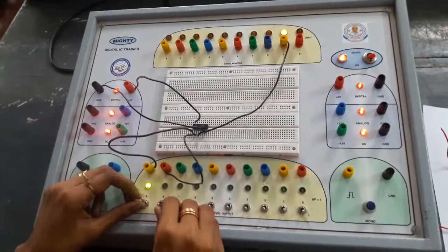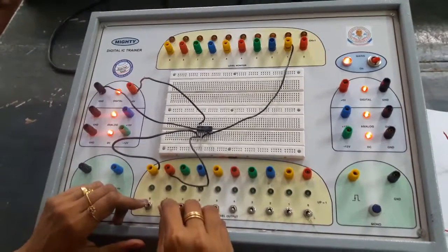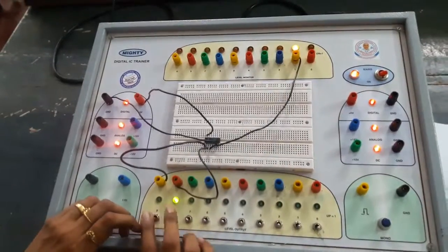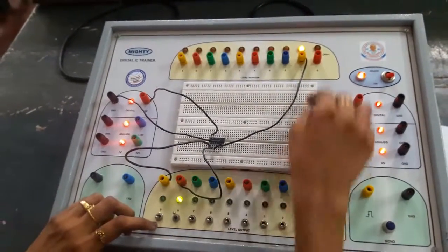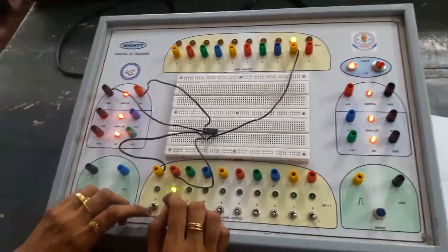Now assume the opposite condition. The switch that is in the ground floor is in off state and that in the top floor is in the on condition. Then also what will be the output? Since both the switches are in the opposite condition, the bulb will be glowing. This is the application of the XOR gate.